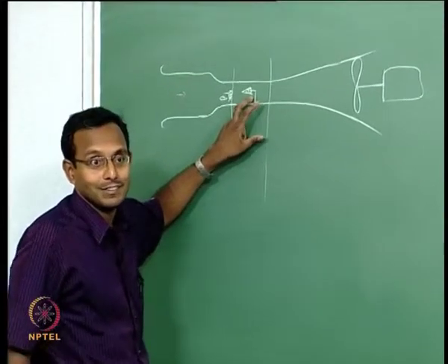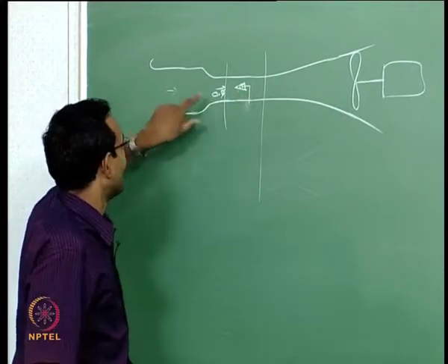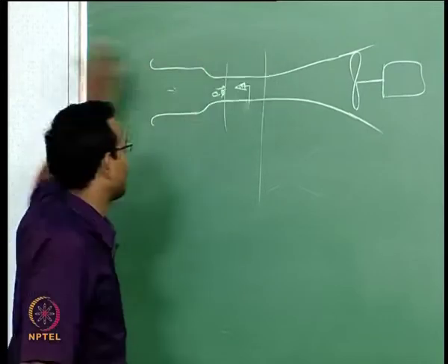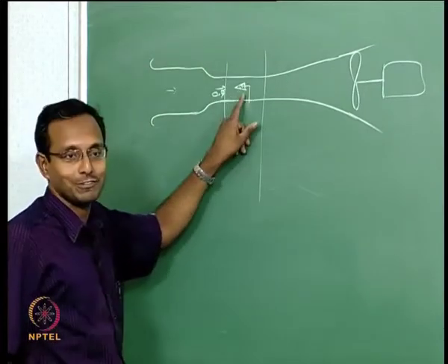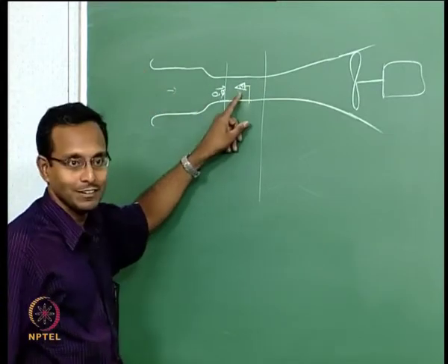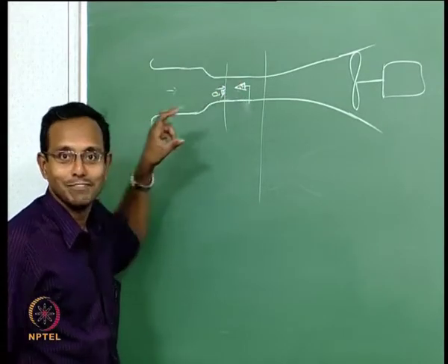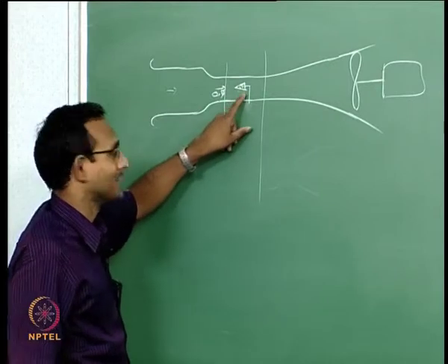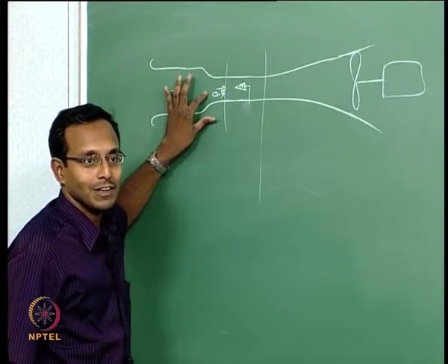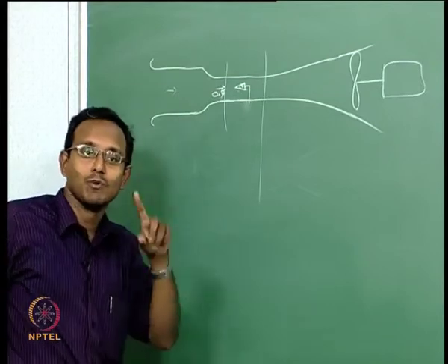What will happen? That flow never happens, it resets everything and then says this point is M equal to 1 and the Mach number is not 0.9 but lesser. It resets everything and decreases the mass flow rate upstream. There will be accumulation, if you think about it from the point of view of Rayleigh flow and Fano flow we discussed. If the choking happens earlier, or I extend the length or decrease the area more, similar to extending length in Fano flow, I am going to say if resistance is more, there will be compression waves coming, changing the flow speeds in front of it. I wanted Mach 0.9 here, but I may get only 0.85 unless I do some more things.